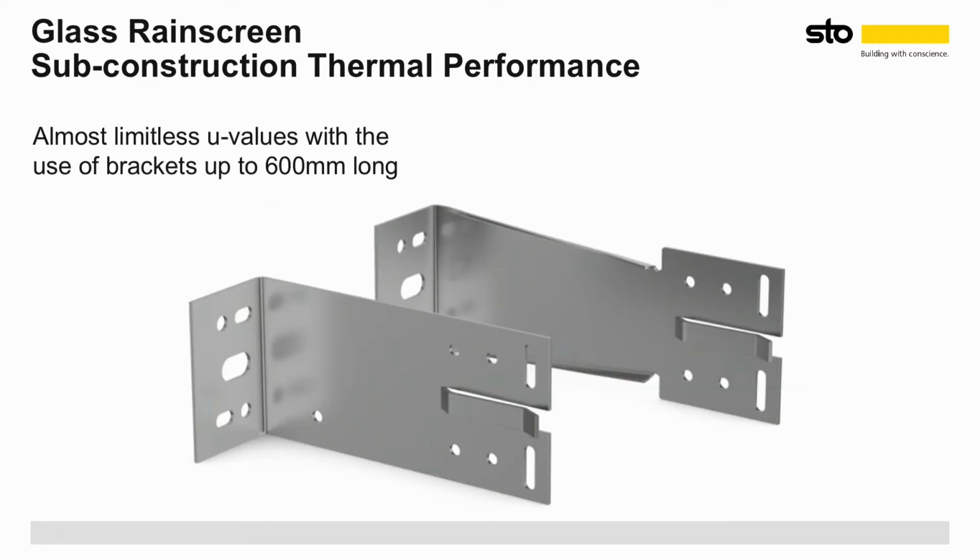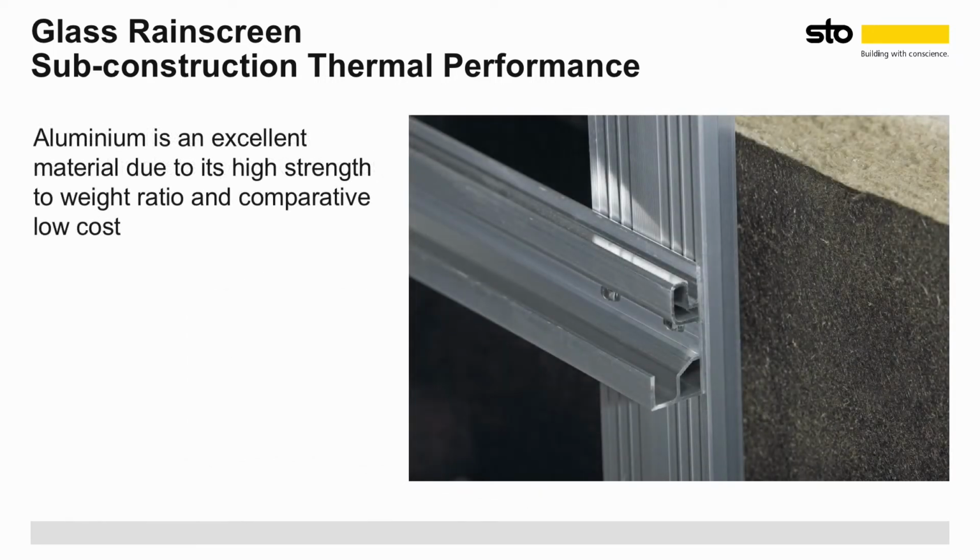Almost limitless U-values and insulation thicknesses are possible, with brackets available up to 600 mm as standard. Longer brackets can also be made to order. Insulation thickness is only limited by availability of fixing dowels. Aluminium is an excellent material due to its high strength-to-weight ratio and comparative low cost, and is therefore most suitable for use as supporting profiles.